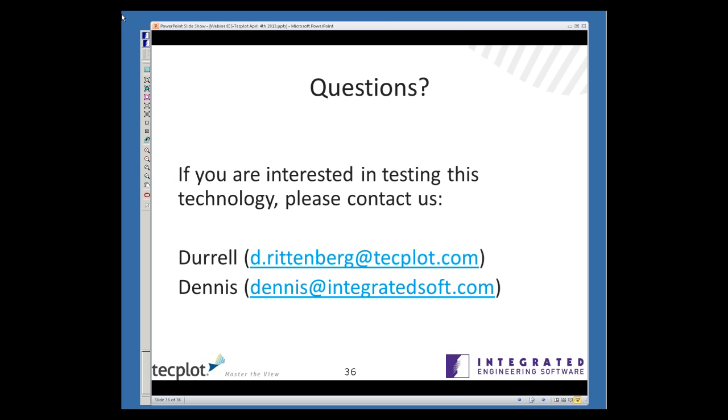So, let me just add one little clarification: Dennis is dead on with that. There are a lot of folks now investigating axial flux motors because of their usefulness with electric vehicles, being able to fit inside the wheel of an automobile. And there is a regime where you can try to cut one of those axial flux motors over a small region and sort of fold it out, if you will, and you can get pretty close. You can lay it out and it's simulated almost like a linear motor, using a 2D approximation, and sometimes you can get pretty close with that. But most people, 80 to 100% of the time, are trying to use the 3D approach. At one point, you have to abandon it and say, okay, now I need to get a little bit closer on my answer. Right, and that seems to be typical across industries.